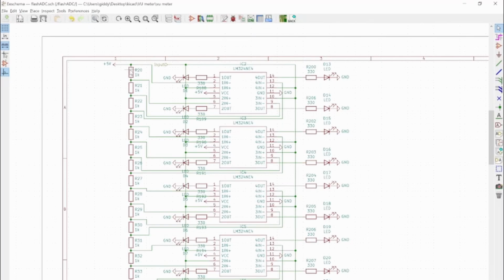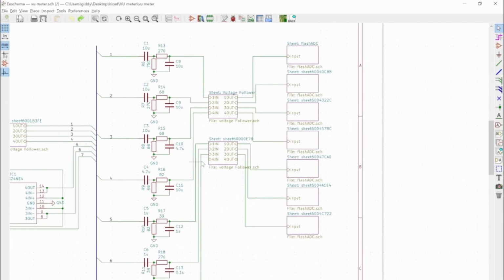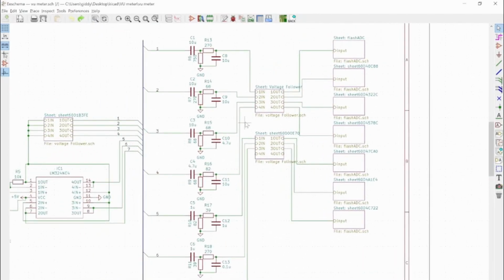But also what we could do is, instead of just having voltage followers after the filters, we could have more amplifiers, which would also help, because I'm not sure, if we had a voltage with a peak of 3 or 4 volts and I had the gap separation bigger, whether that will give us a better output on the LEDs, or whether what we've got now is working well. I don't know. So that's that.